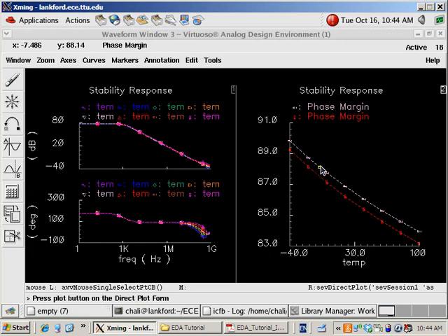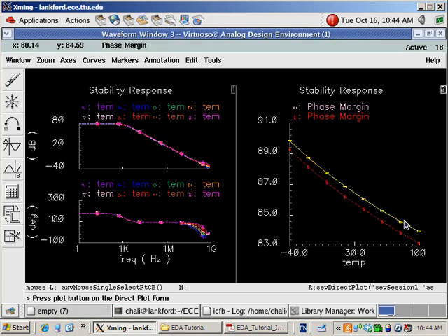Okay, so let's see. At a different process corner, the phase margin will be different, right? So at different process corners, you also have different phase margins. So eventually, when you design something, you have to exhaust all the temperature possibilities combined with all the process corner possibilities. And what's worse, they normally call this the PVT corner, and you also have to combine it with the supply voltage corner and find out what is the most challenging case.